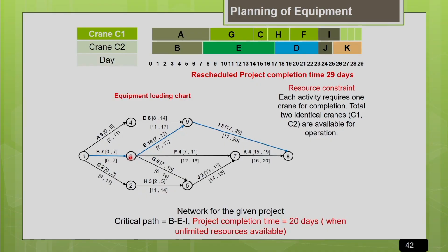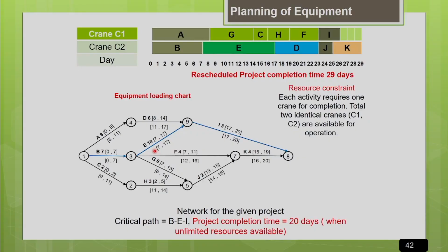So generally, first we allocate the resources to those activities which are critical, that is, whichever have 0 float, the least float. Then allocate the resources to those activities which have the second least float. So we are allocating resources in the order of criticality of the activities. Instead of float, I can also go by the least latest start time. Both are going to give you the same result, but it is more convenient to use the least latest start time approach.